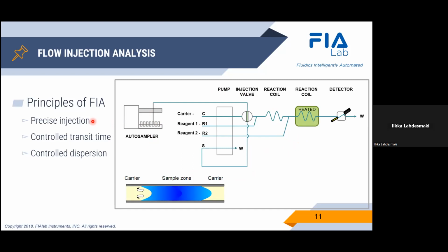And it's very critical that the sample volume remains the same from one measurement to another, to another, to another. Presently, this is possible thanks to the tremendous technical development that has taken place over the last 30, 40 years in the field of injection valves, as it was necessary for ion chromatography and liquid chromatography purposes. So that part we've got taken care of.